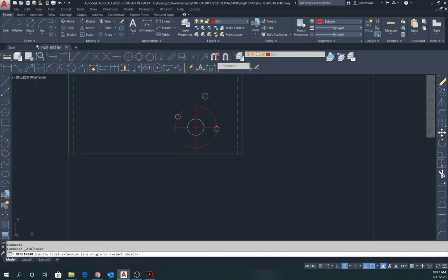We're going to start our dimensioning. So again, we choose dimension. We select here, we select here, pull down 2.925. Another dimension, we select here, select that center. 3.137. So here it looks like I must have typed in a wrong dimension, because it should be 3.175.